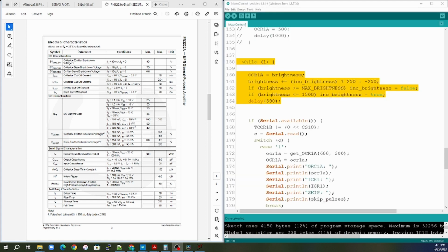So in my prior video with the 1 megahertz PWM from Arduino, I'm basically using that same code in order to output a 50 hertz signal that I'm then going to PWM to the DC brush motor. So same basic concept that was going on with that video. I'm just reusing the code here in order to move the DC brush motor at different speeds. So let's take a look at this on the scope.